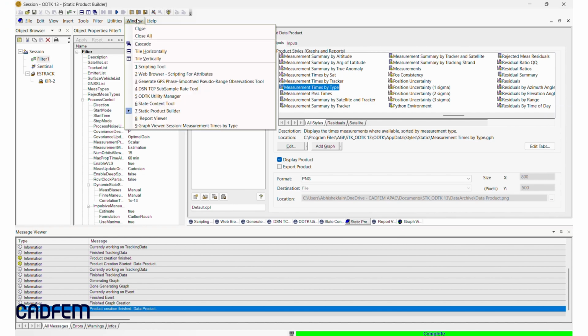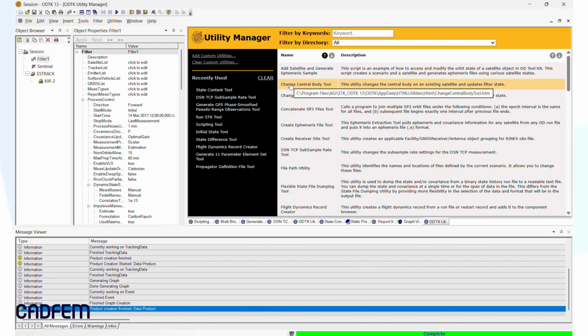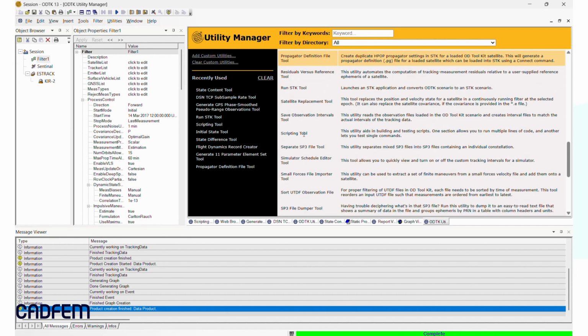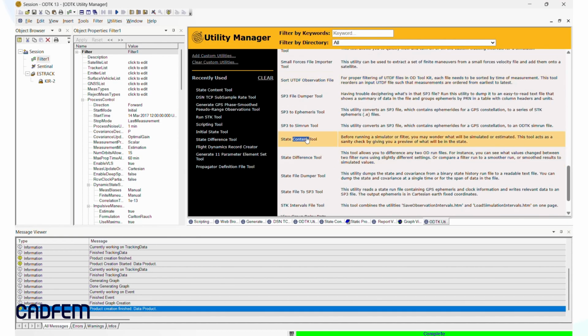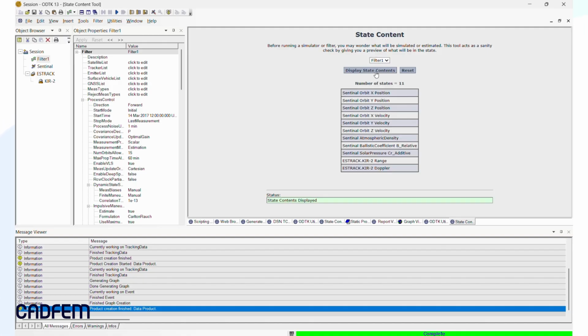Using these measurements, the filter estimates the spacecraft state and generates information that can later be used to produce ephemeris data for downstream analysis. Next, we configure the filter outputs. Within the filter properties, we enable smoother data generate, allowing smoother data to be produced for later post-processing.